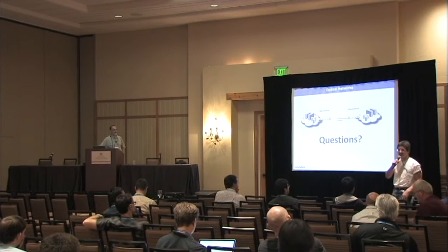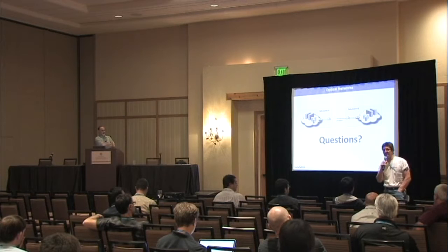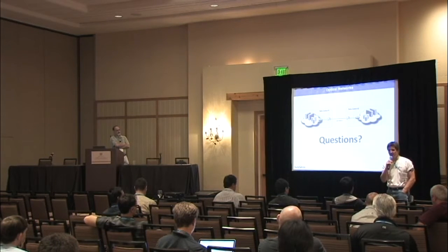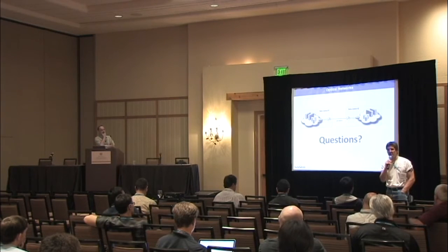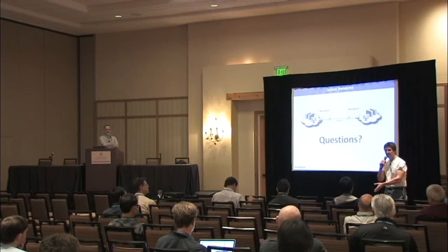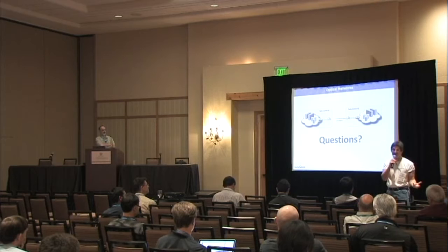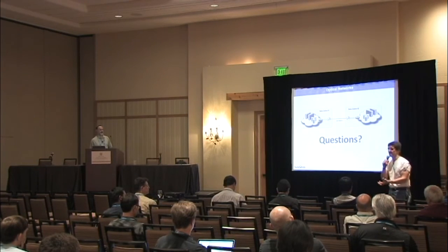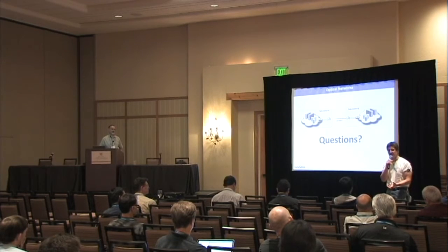Well, I'm Matt Putak from Yahoo, I'll answer from the perspective of someone actually putting optical networks in place. The question is sort of meaningless, because it's going to depend upon what point you look at a network, and networks evolve over time, where we start off with a solution that has transponders as external units. We tended to migrate from external transponders to integrated optics within the router platform. And you have kind of the pendulum swing of, okay, the external transponder makes sense initially, then the optics technology gets better and better. You put the integrated optics into your routers. You reduce the operational complexity of your network by reducing the number of boxes that you're dealing with. Then the bandwidth demands go up, and you start to find that the integrated optics aren't supporting the next generation level of speeds that you need. So you go back to external transponder units again, and an external transport network that actually has the speeds and the distances you're looking for.